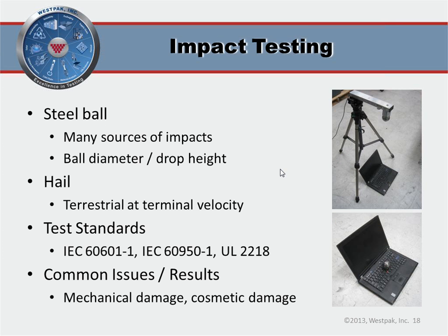They're the most fragile. Like before, you can either test to level or test to failure, so define a minimum passing requirement and an extreme passing requirement. And with your pass-fail criteria, think about cosmetic damage the user may not like, functional damage where the product actually stops working, and then safety issues if there's severe mechanical damage or any safety issues exposed. Good example would be glass. If you break most modern safety glass now, there's no significant cut hazard. If your product had glass in it or something electrically live, something very similar would apply.